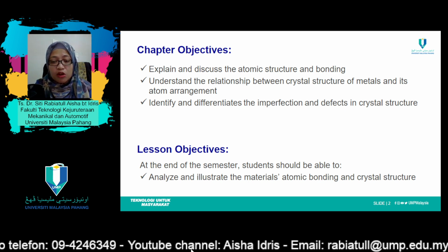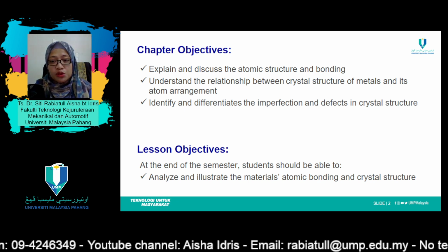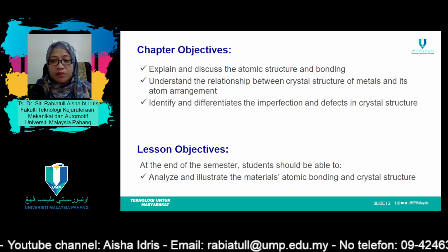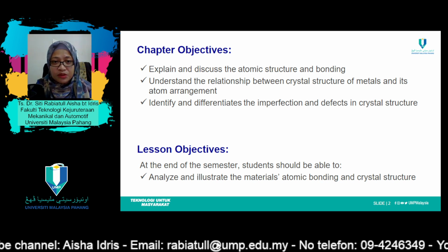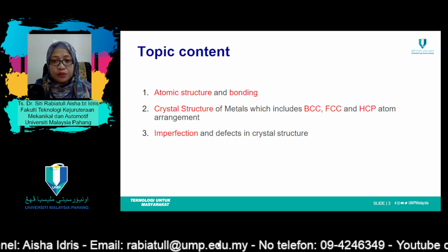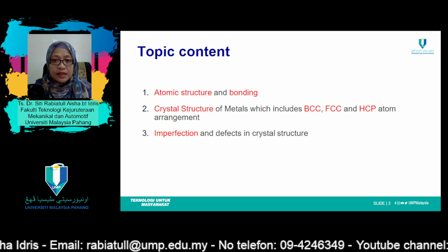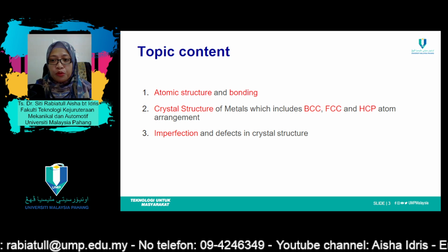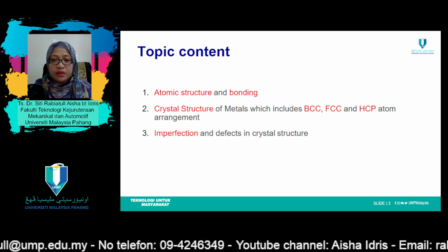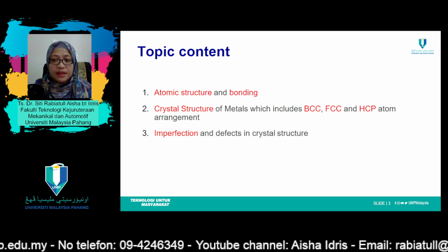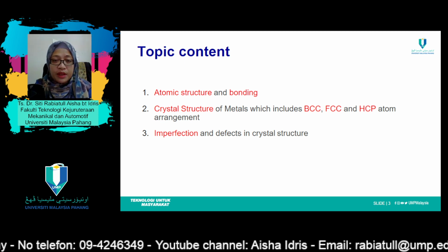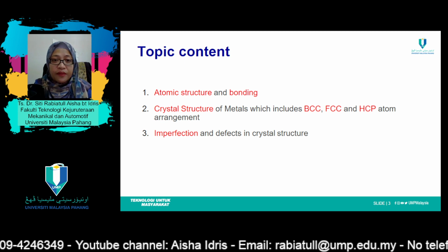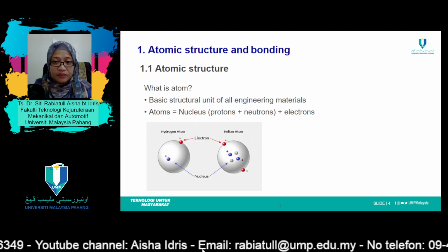As for the lesson objective, at the end of the semester, students should be able to analyze and illustrate the materials atomic bonding as well as crystal structure. So for today, we are going to look at these topics. Number 1, atomic structure and bonding. Number 2, crystal structure of metals, which includes BCC, FCC, and HCP atom arrangement. Number 3, imperfection as well as defects in crystal structure.